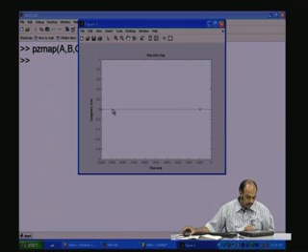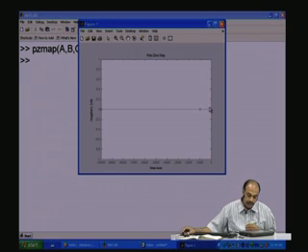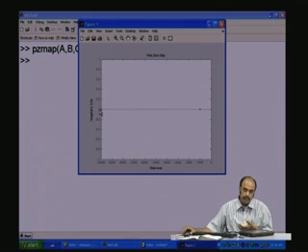The pole of the changed one, the one which you see here in green, is at minus 10,000. It means that the pole is much further away from the imaginary axis, and therefore, it is faster. As the pole moves more and more away from the imaginary axis, the system becomes faster and faster.